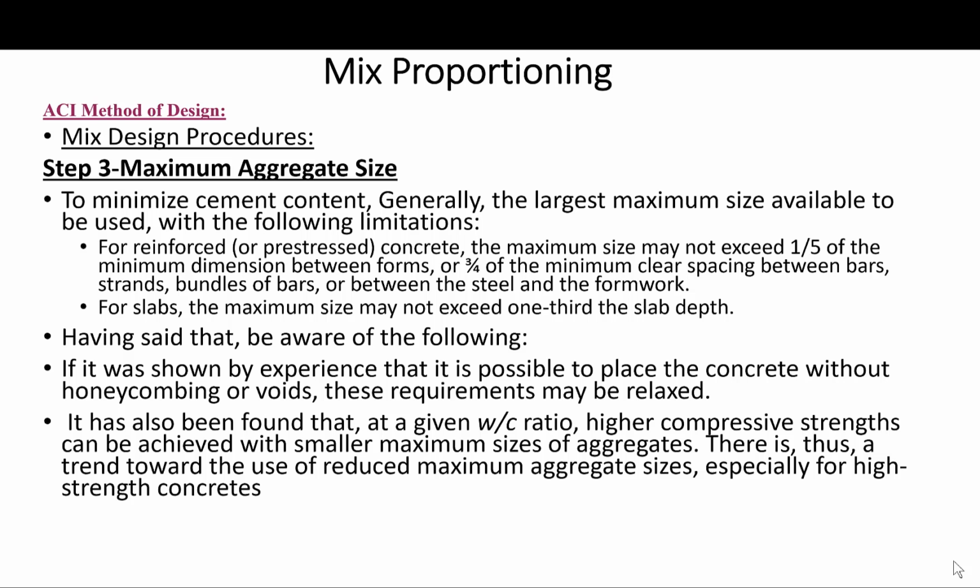So you want to maintain uniformity throughout the job, not to specify various mixes for different parts of the structure, unless there are other requirements. But if the size of aggregates is the only difference, I would unify it all based on one size, just to make sure I have uniformity, and I will reduce the probability for error.